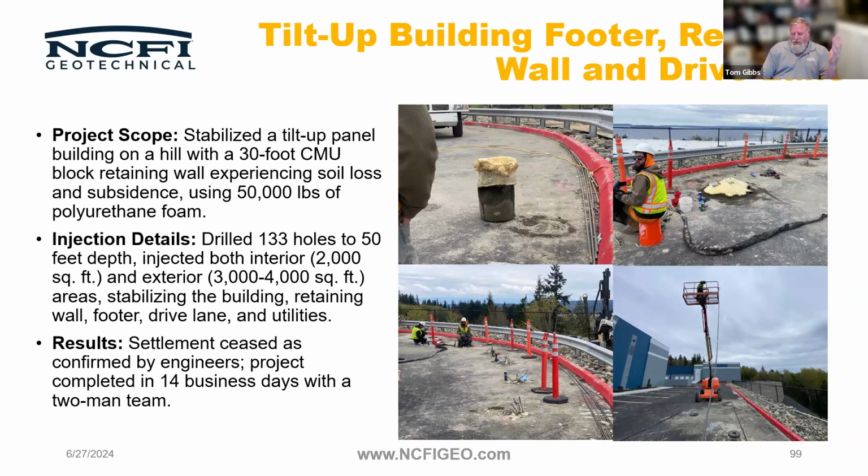If you've lifted a structure, you essentially created a void in doing so. And yes, those piers are designed to carry that load over the distance, but it's really good insurance to try and reduce that by placing something in it. And it's really tough to get fill back up underneath there. So you can spread that load out a lot better if you fill it with something like this.